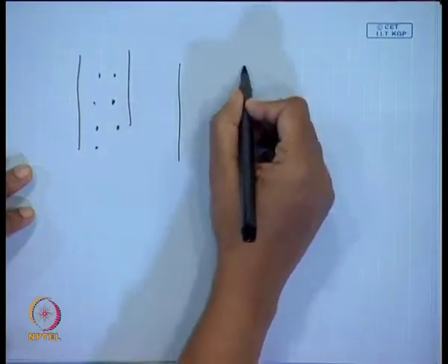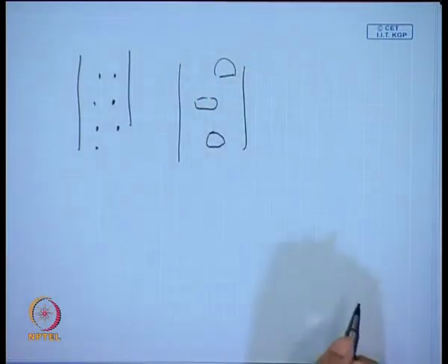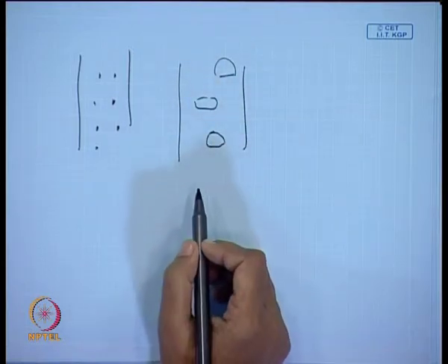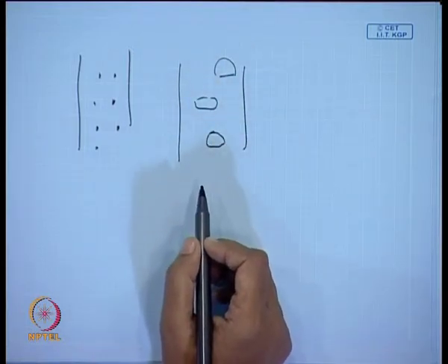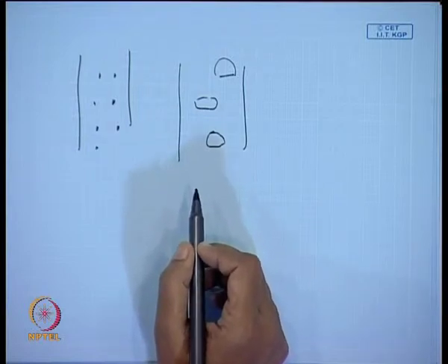The moment the bubbles become larger and get deformed, the uniformity goes away. Under this condition also the homogeneous flow model does not apply, but we apply it, see how much deviation there is, and then we suggest some suitable correction factors.